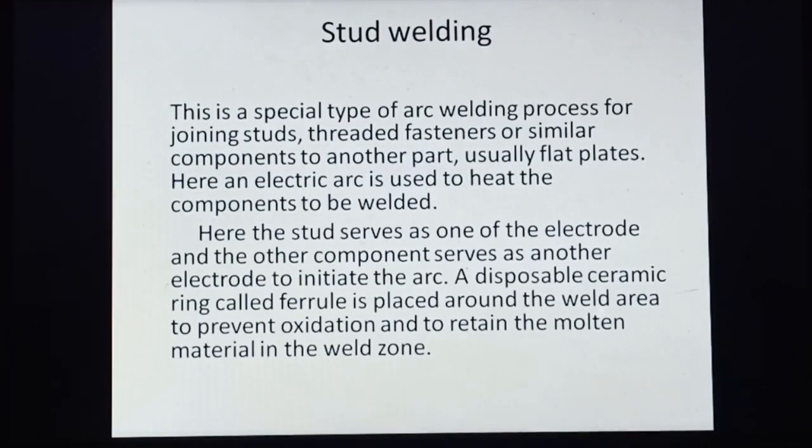Then stud welding. Stud welding is a special type of arc welding process for joining studs, threaded fasteners or similar components to another part, usually flat plates. Here an electric arc is used to heat the components to be welded. The stud serves as one electrode and the other component serves as the other electrode to initiate the arc. A disposable ceramic ring called a ferrule is placed around the weld area to prevent oxidation and to retain the molten metal in the weld zone.